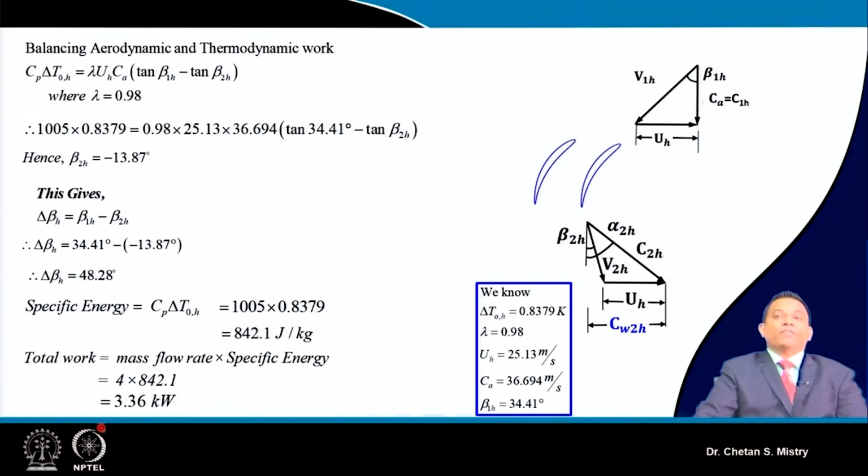So basically when we are calculating this total work done at different stations, we will be averaging it out, and that will give us the power that is required. We will see what is the difference in power when you are using your free vortex concept and when you are using your fundamental concept. But this is a way in which we are calculating our total work done.